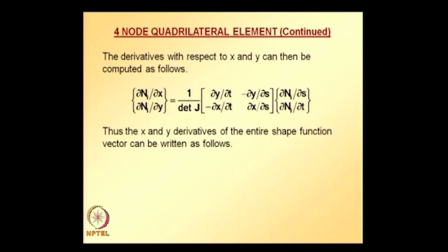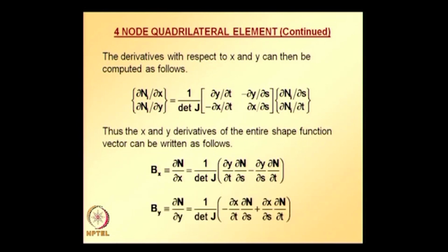Thus the xy derivatives of the entire shape function vector can be written, writing shape function derivatives with respect to x as a separate vector Bx, B subscript x. We can write this relation from the previous equation, and similarly By.